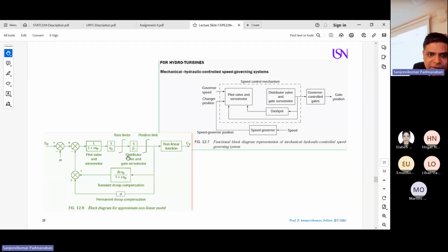So again, you integrate with the gain. So it's a gain, you understand? This gain is combined together, integration is done. So it's the integrator with the gain tau g. Then you put a limiter in order to fix the value. It should not exceed the minimum and the maximum value, because integration, as I said, is a summation with respect to the time. You can exceed the value. In order to limit, we use a limiter.